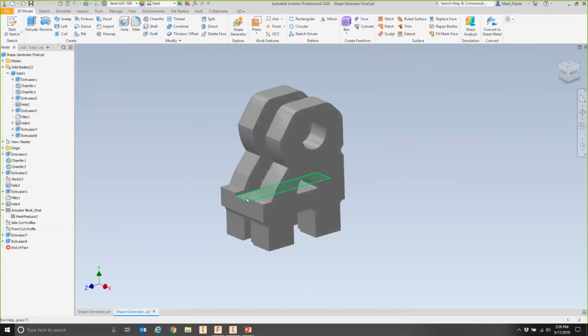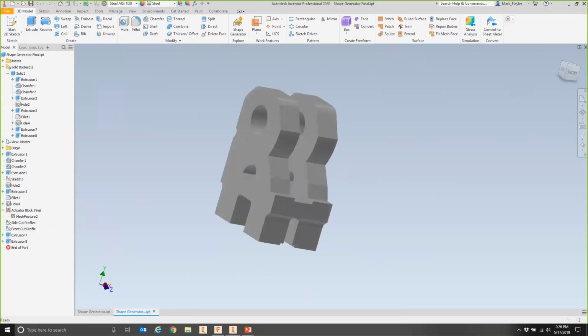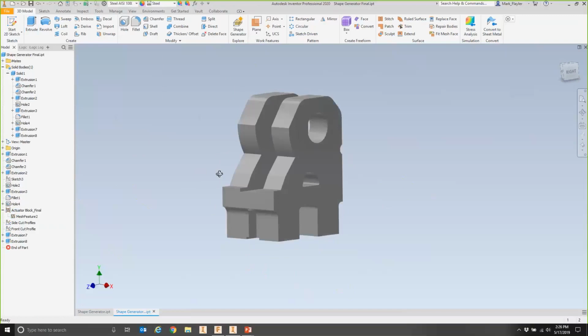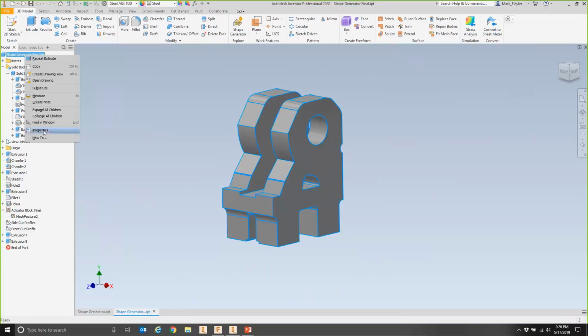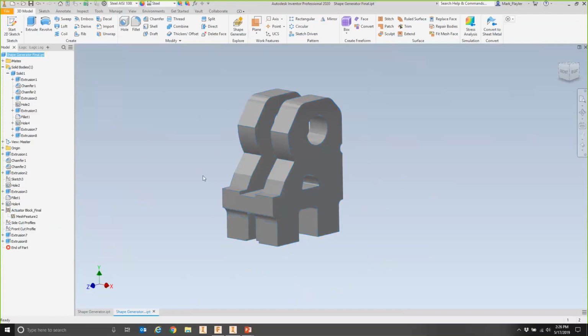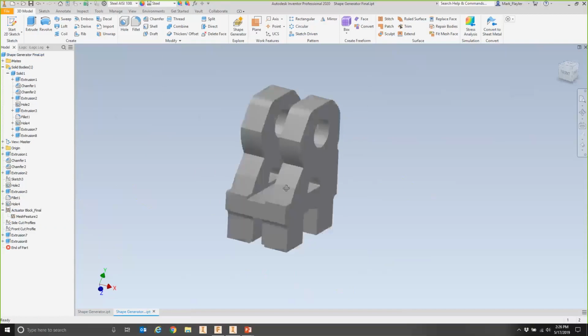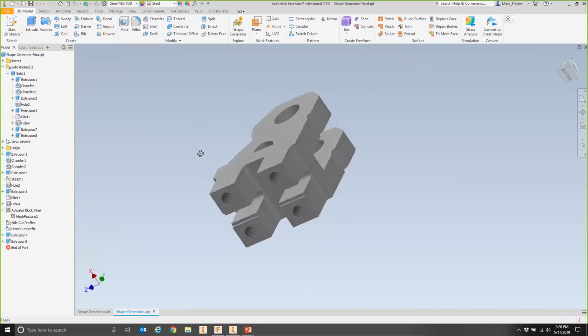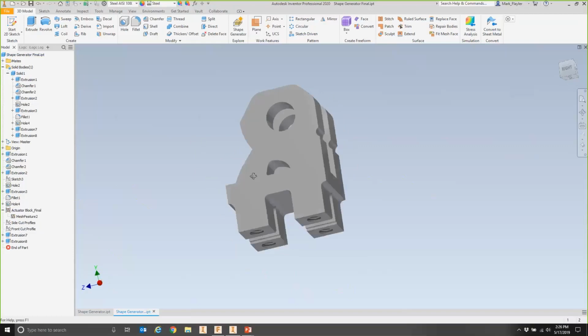Well, maybe close to finished. You might still come in here and tie up some smooth edges, get rid of some sharp corners on this perhaps, but essentially there's my new shape. And this particular piece, let's see where the weight ended up. I got down to 3.364 pound mass. So I can probably keep reducing a little bit more out of there, maybe change my material capabilities a little bit, but it did maintain those regions that I wanted.